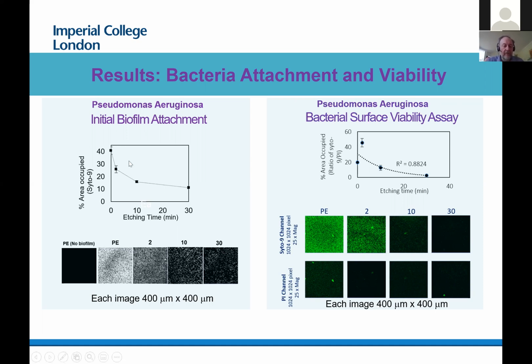And that's plotted in the graph you can see above. So by the time we get down to our 30% treatment, we have probably something approaching about 10% of the area attached. So certainly it's not as clean as the material that didn't see any bacteria, but it's probably 4 to 5 times less bacteria than the as received material. So that's the attachment, that's the population of species.